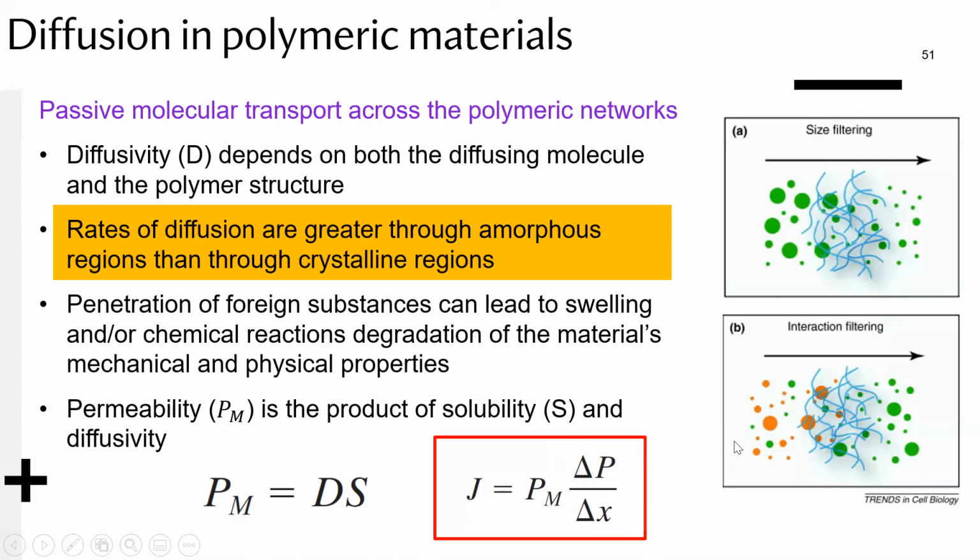Now, that is the pressure difference between the two sides of this barrier. What that means is that if you increase the pressure difference, you'll get a greater flux. Is that correct? Yes, because if you increase the pressure, it's going to make these molecules move faster, hit each other more frequently, and also have a lot more kinetic energy and momentum to actually get through this material.